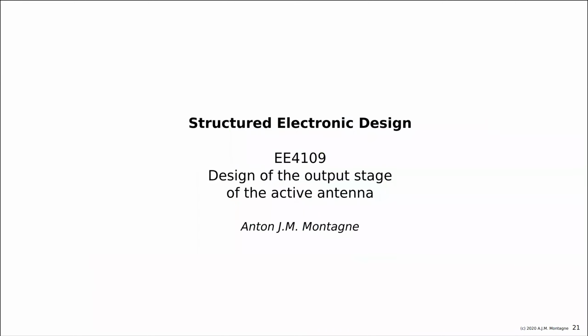So the output stage we also did already do. Yeah, we already designed a simple CS output stage, but now I would like to go, because of the efficiency, to a balanced output stage, a complementary parallel CS stage. That is what I would like to have as an output stage here for this amplifier.